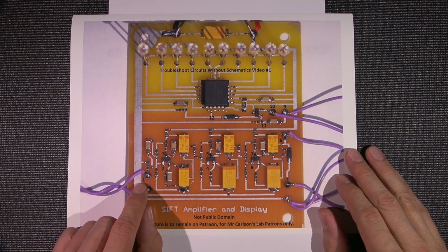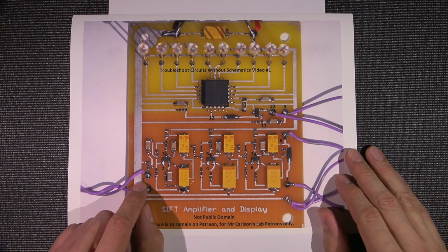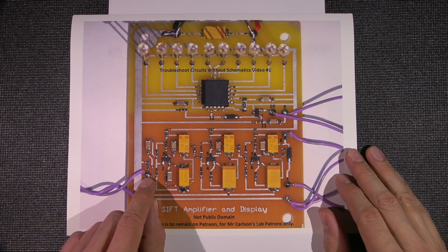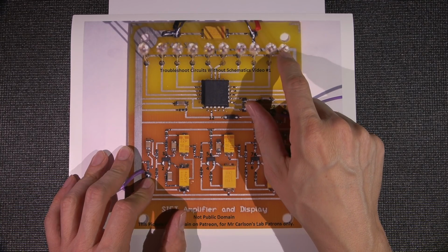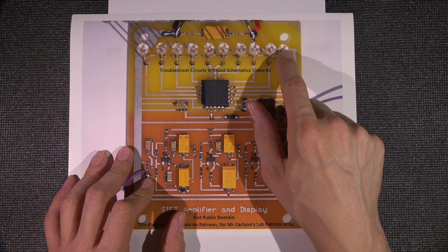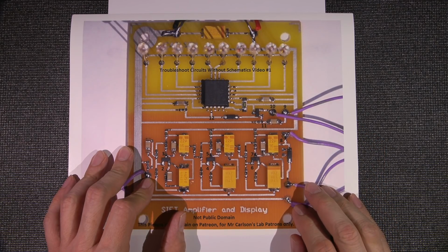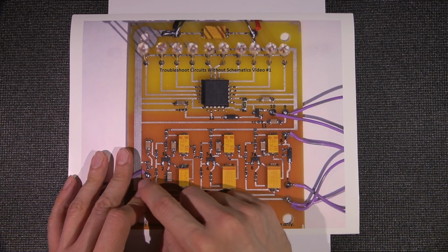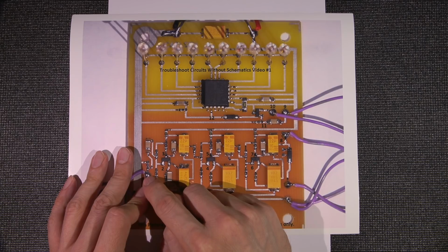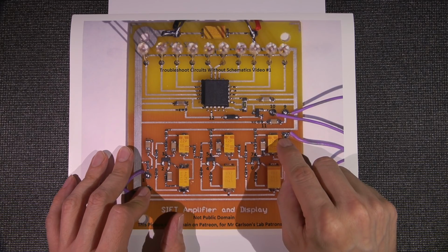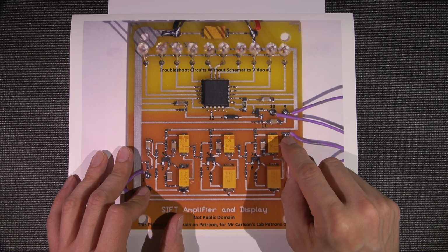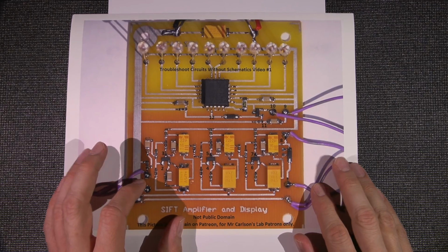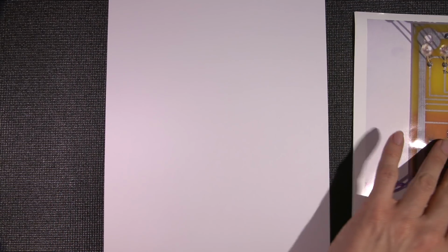So we already know that if we feed 27.5 microvolts into this area right here, it will light these LEDs right to the top and comfortably light this last LED. When I fed this with 27.5 microvolts, I took a reading at this point with my oscilloscope, and I got 1.85 volts out. These are both RMS readings. So we can do our calculation from that.